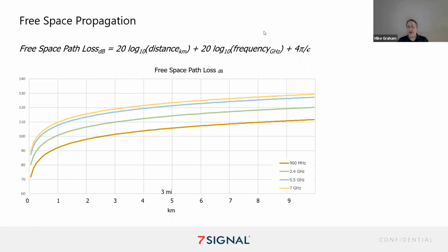And sometimes they're very empty and sometimes they're very full. It's very clear if you look at signal strength on the access points on an empty versus a full building that there is a lot of loss. I've seen 6 and 8 dB change in signal strengths just between empty and full buildings. And I have to assume that that's mostly just the people soaking up signal.